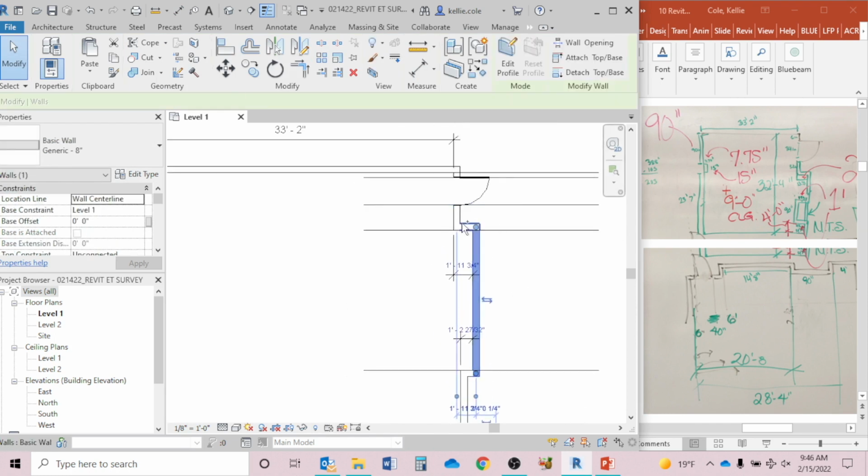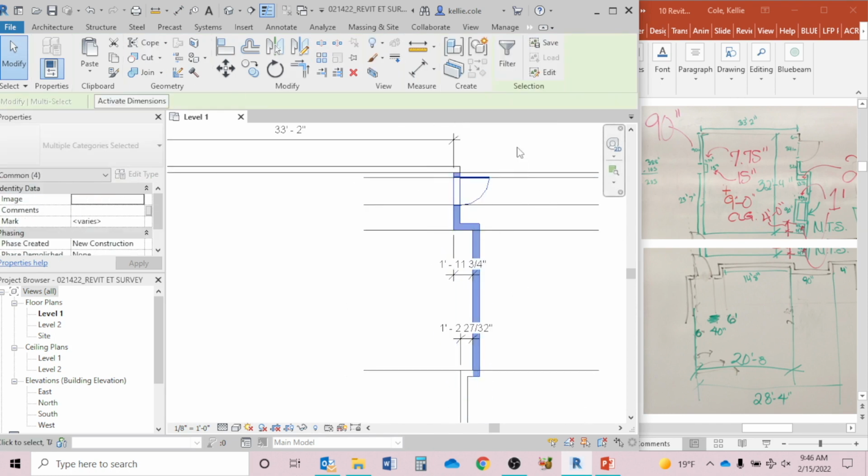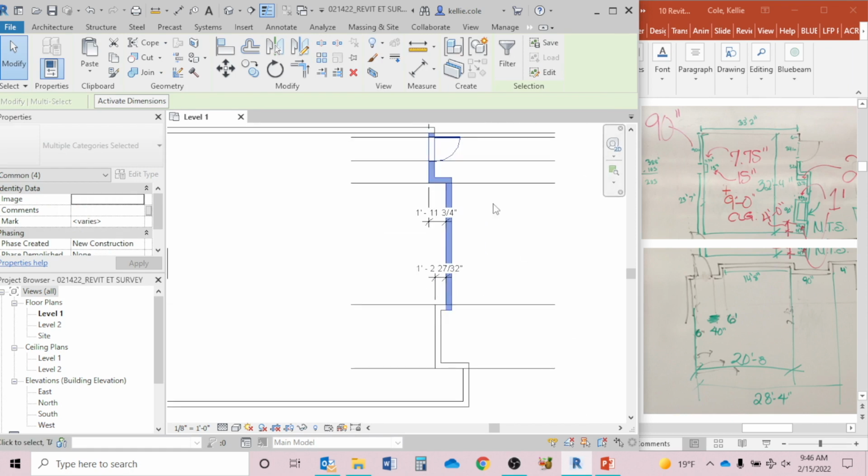These walls, maybe we pin them so they don't change, are set. So let's grab all of those. I just hit Control while selecting different pieces to add it to my selection. P-in to pin those.